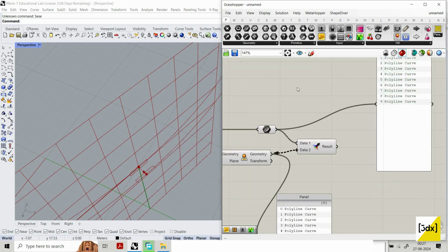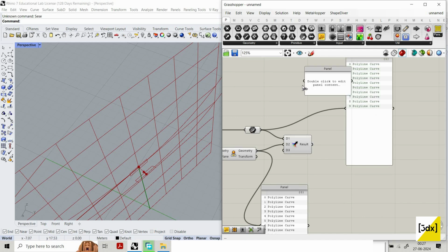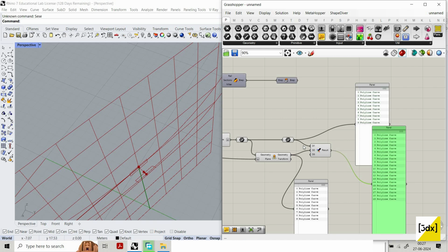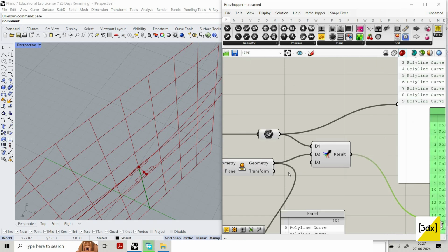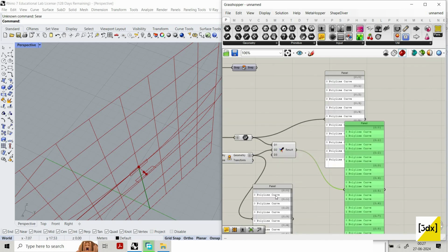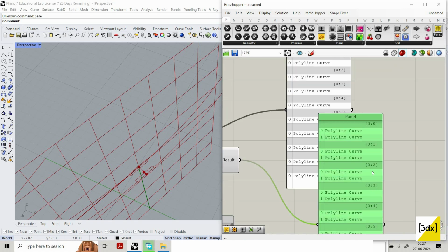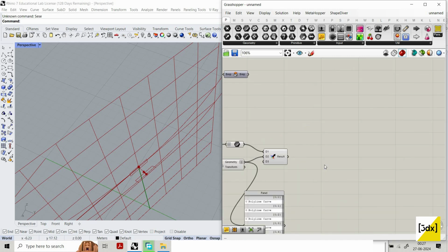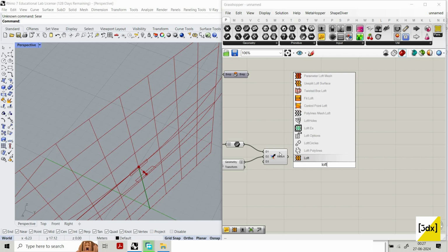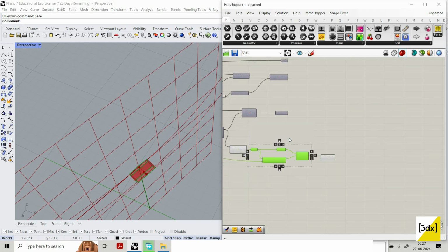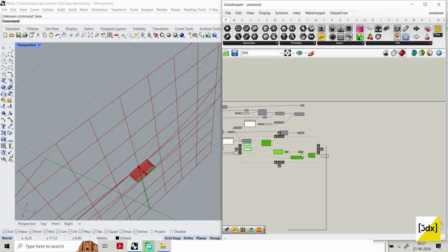So if I use merge, you can see it creates a single list. But in this case, when I grafted both the elements, this one grafted and this one grafted, you can see this curve has been matching with this curve and it creates a branch like this. That's why I created a branch. So these two curves loft. So I'm just manipulating the data in a way that it lofts. It matches the curve for the lofting. Now we created what we want.